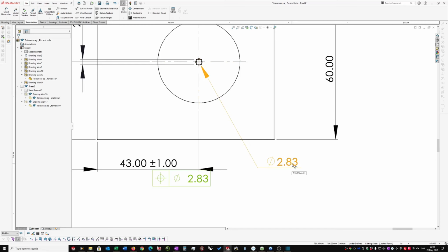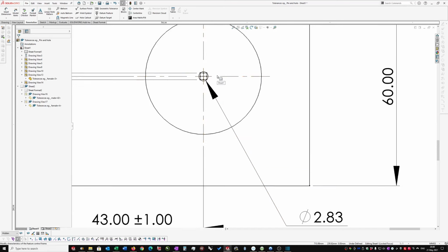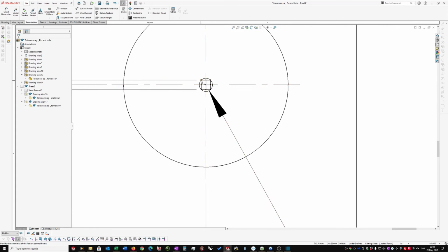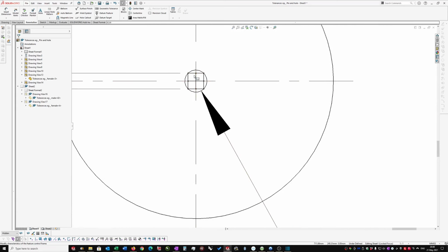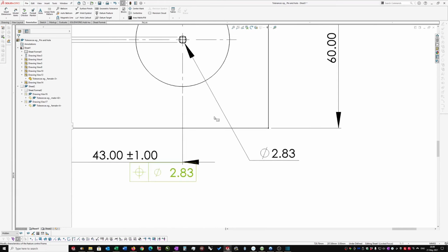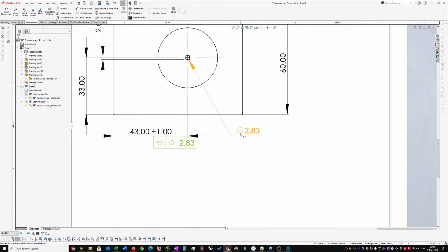So it's giving you a significant amount more tolerance leeway whilst acknowledging that the limits are exactly the same as the square, because if you took that point and you distributed it equally in a circular fashion, that's what you get. You wouldn't get this little bit in the middle here. You wouldn't be restricting your tolerance to a square, which is unnatural. So that's what that's doing. It's giving you more leeway.